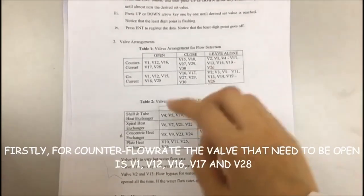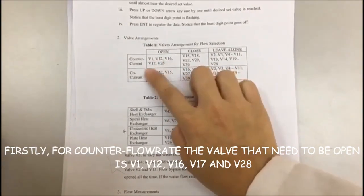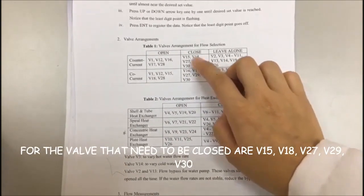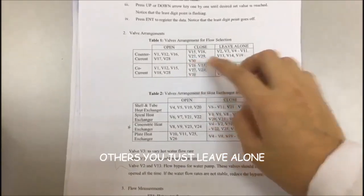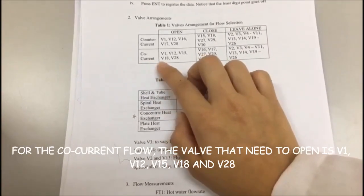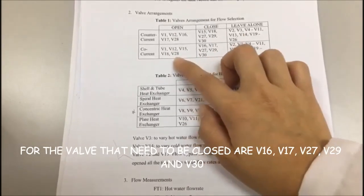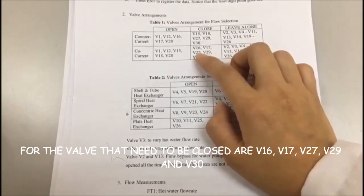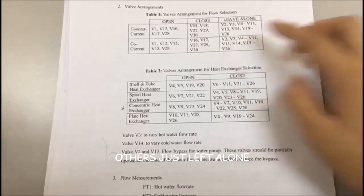Firstly, for countercurrent flow, the valves that need to be open are valves 1, 12, 16, 17, and 28. The valves that need to be closed are valves 15, 18, 27, 29, and 30. Others you just leave alone. For co-current flow, the valves that need to be open are valves 1, 12, 15, 18, and 28. Second, the valves that need to be closed are valves 16, 17, 27, 29, and 30. Others you just leave alone.